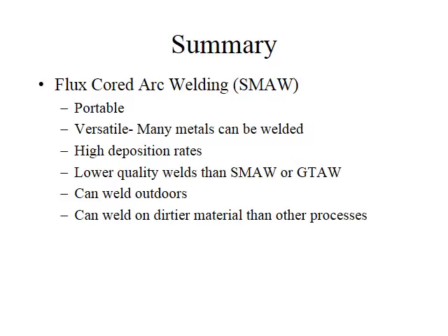In summary, flux-core arc welding is an arc welding process in which the heat for welding is developed between a continuously fed consumable tubular metal electrode wire and the workpiece. As the metal electrode melts in the welding arc, it becomes the filler metal for the weld deposit. The decomposition of the flux contained within the tubular electrode provides protection from atmospheric contamination. The protection is achieved by gases derived from the breakdown of the flux in the electric arc. Supplemental shielding gas is usually used to give better protection to the metal in the weld puddle.